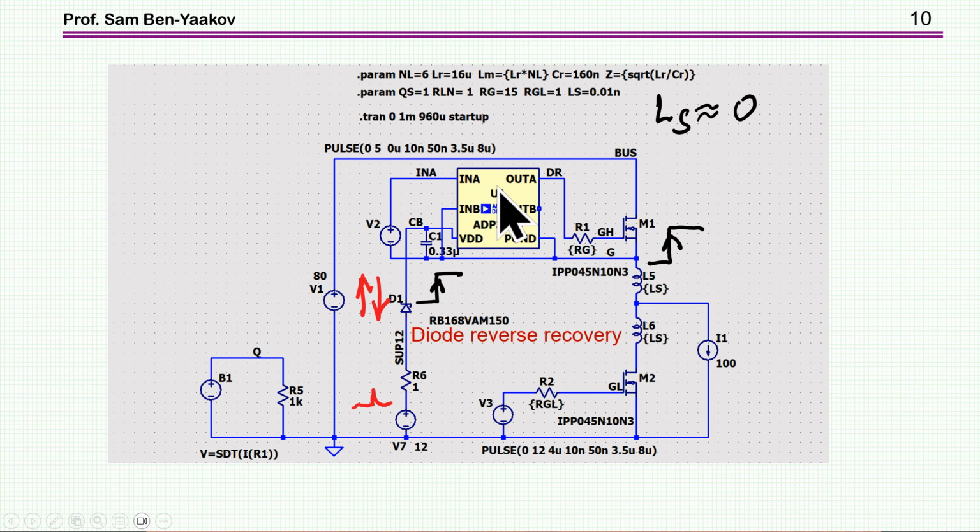because the transistor is turned on at the end of the dead time. So we have a conducting diode, and the voltage now goes up, so there is a reverse voltage on the diode. So there is a reverse recovery phenomenon. There is a negative current going through the diode because it was conducting, now it's not conducting. And consequently, we are going to have a spike here. And this spike is going to get into this power supply, so you have to worry about it. And this is why you need a diode, which is a fast diode.